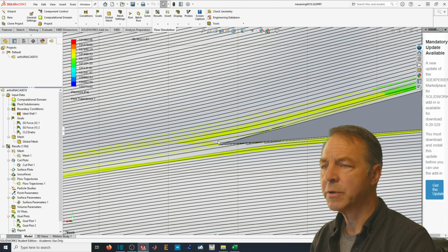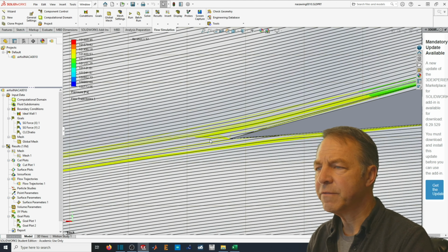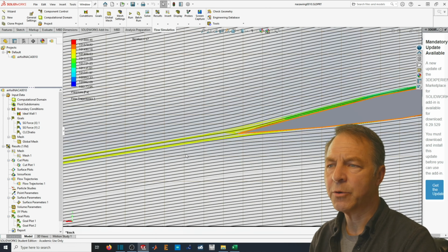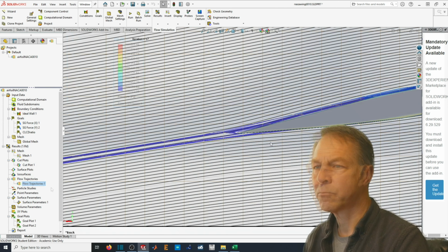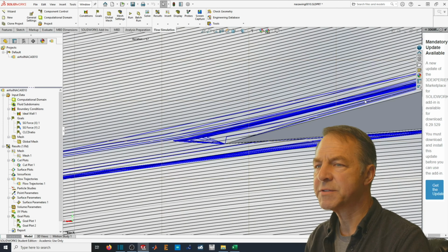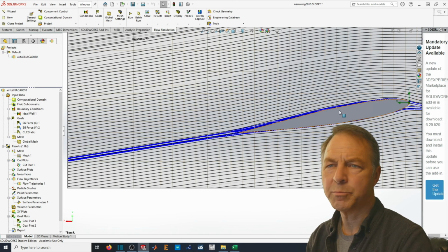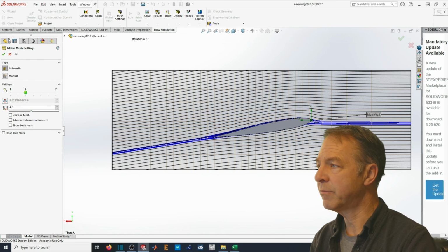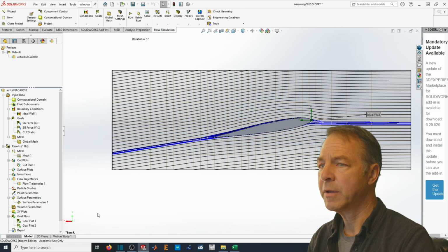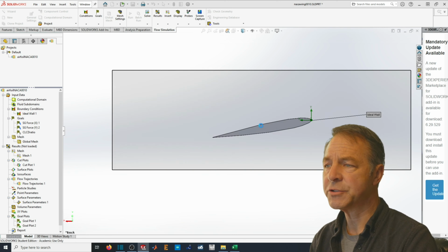And looking at this zone, there's something funny going on in here, but it's very hard to see given our flow lines. Now maybe I'll try to change some of the colors there. So now you can see that our flow lines are quite jagged, but they're doing something odd in the backside of that wing. I'm just going to go to a mesh level of 3, let's say. And I've changed nothing else. And I'll run this. I'll run it as a new calculation.